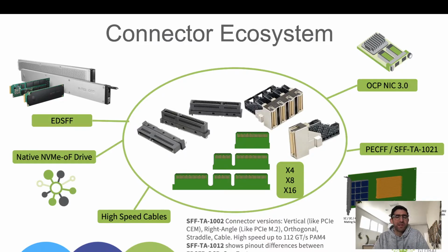And as we move to PCIe Gen 6 and beyond, when you go away from NRZ to PAM4 and you go to really high speeds, above 50 gigatransfers per second, all the way up to the connector's rating of 112 gigatransfers per second, we have a bunch of longevity in this connector ecosystem.